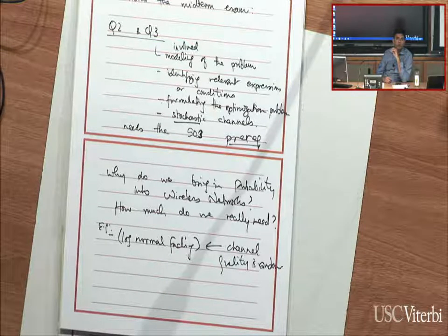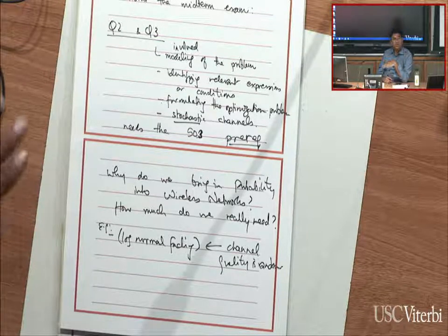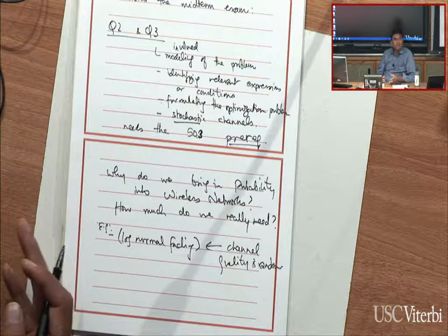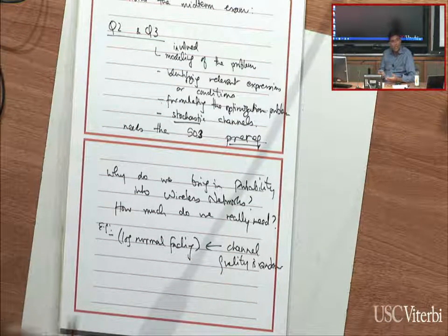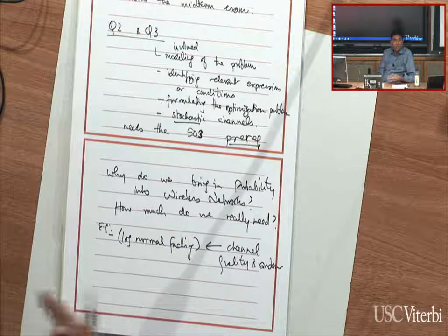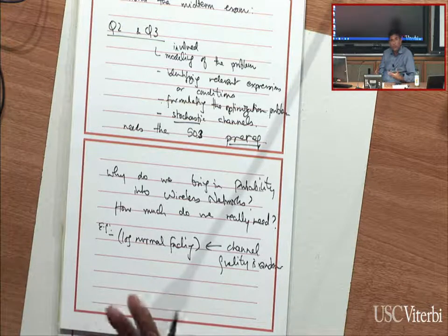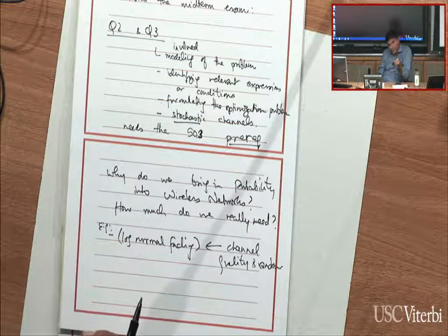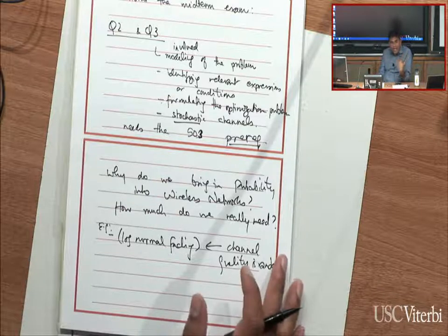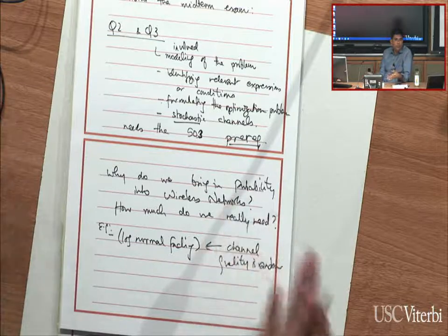Part A solves that problem without worrying about the randomness of the channels. Part A says, let's forget about the fact that things are random. I just look at, on average, how the channels behave, and I'll answer that question. But Part B says, we know from our experience, and from measuring data on real cellular base stations, that there's a lot of variation in the signal strength. I can measure that and evaluate what the variance is. I can fit it to distributions, and if I do it in the dB scale, it looks kind of Gaussian. So I actually know that in practice, not only do I get a certain average value, I'm getting instances that are distributed around that average value according to this particular distribution. So the real world has this randomness of channel quality. It's not something we're cooking up to make our lives miserable in this class.